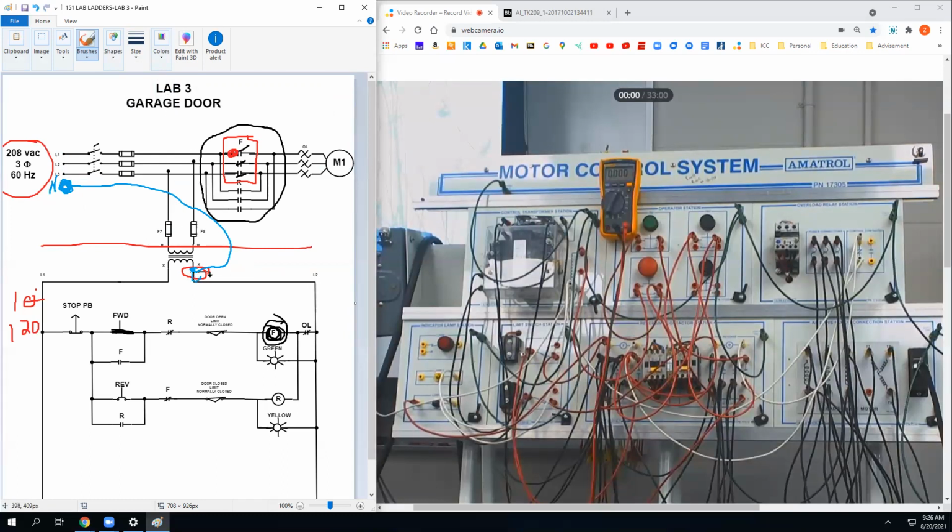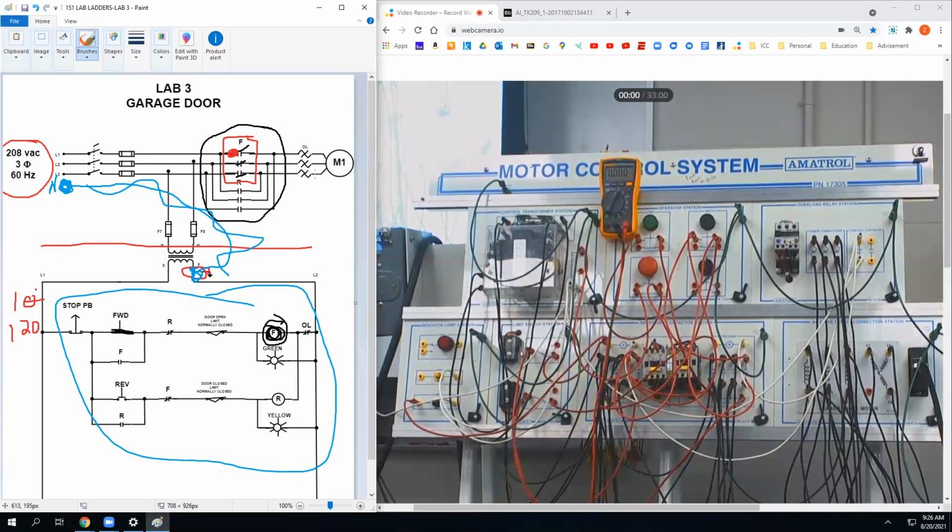And then this guy, you might say, well, hang on, I'll get to that. This guy is going to be your best reference of potential for any of the control circuit wiring, right? Because let's say this wire is not in there. If I check three-phase 208 voltage on one leg, I should have 120 to ground or 120 to neutral. Where I'm getting that neutral or ground from, though, matters. If I get it from down here, I might get some weird readings, right?